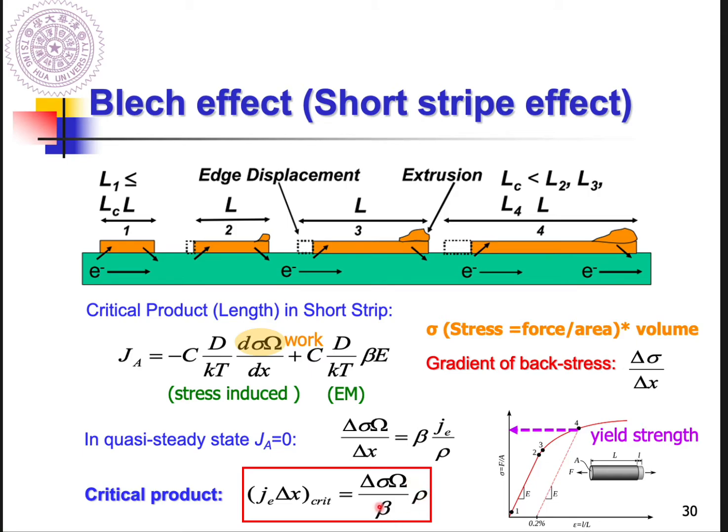So as long as you decide what kind of material you are going to use as a connecting line here, then you can measure the conductivity, atomic volume, the yield stress, and also the effective charge of these materials. And your left-hand side will be more related to the IC design, right? As long as you know what kind of chip or transistors you are dealing with, then you can determine the necessary current density to operate this device.